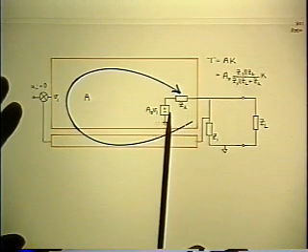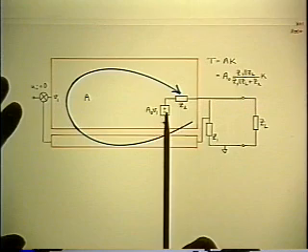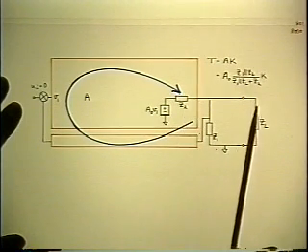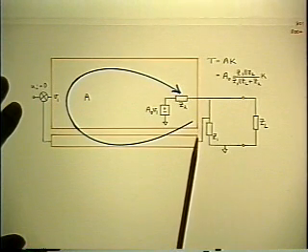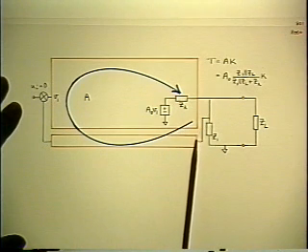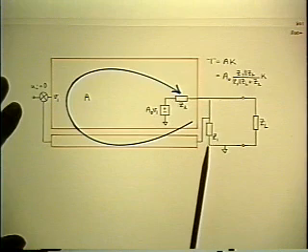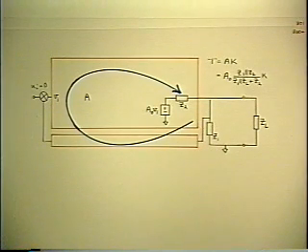So the output of the forward path is represented by the Thevenin equivalent of a generator and a series impedance Z2 feeding into an external load. Connected across the output also is the feedback path, and it usually has a non-infinite input impedance, which is represented by the Z1 in this box, or there's some other impedance there across which the feedback is developed.